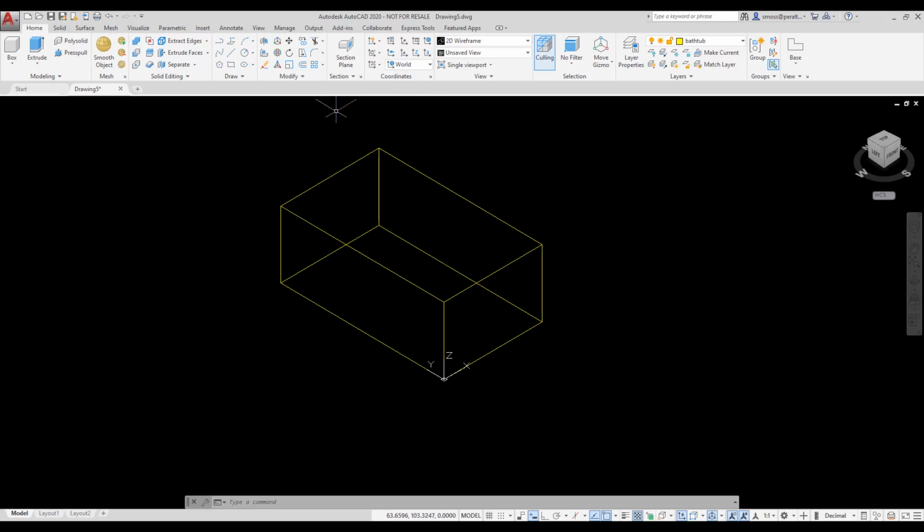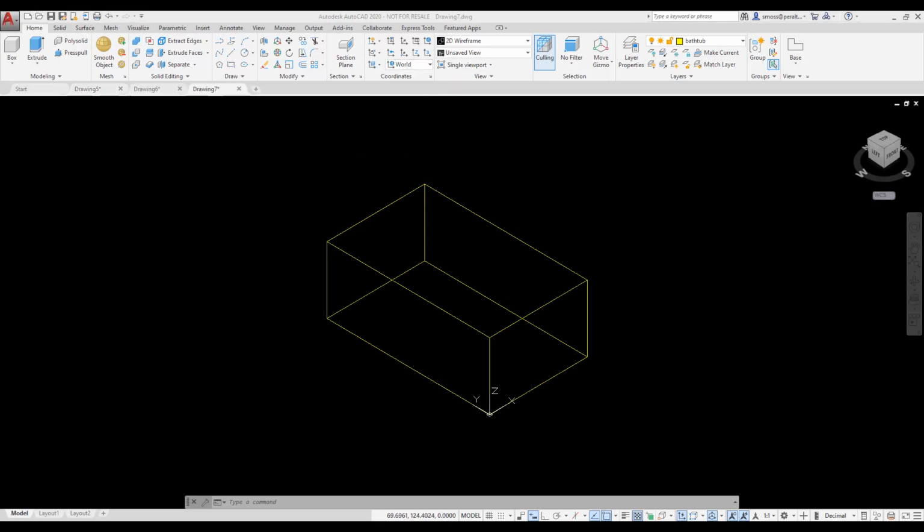By default, I would be drawing on the XY plane of the World Coordinate System. In order to sketch on the top face, I need to move my UCS to the desired construction plane. On the Coordinates panel of the ribbon, there are several preset orientations for the UCS. If I select the different orientations, you can see the UCS rotate, but it remains on the original construction plane.